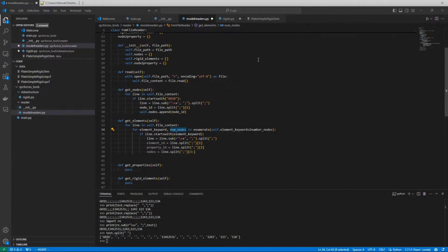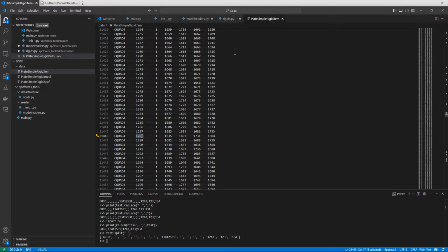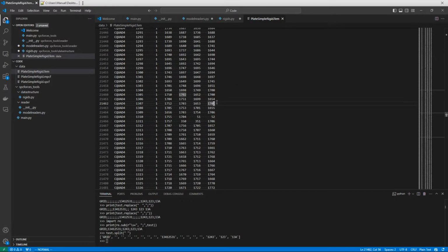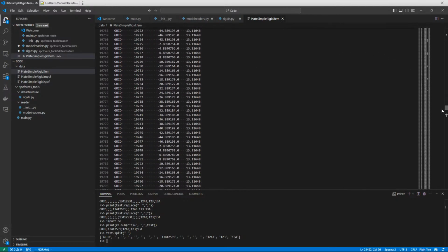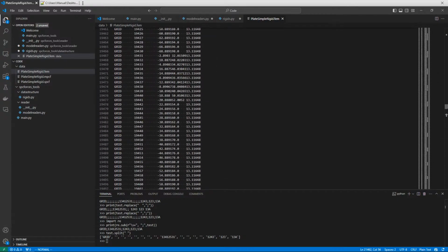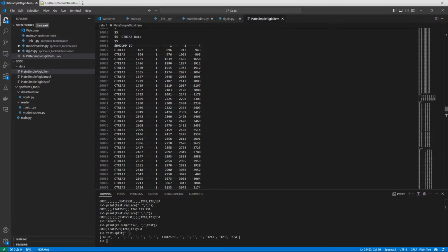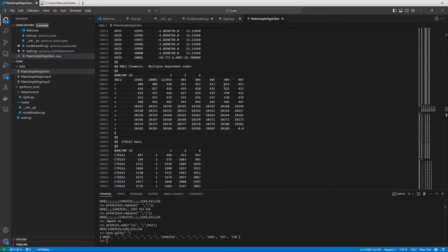By the way, I can think of something here being nasty in the future. If we have a hex element with more than 8 nodes or so, it will have another line with a plus at the beginning. With the RB2 you can see it, and you will have something like this too. So we definitely would like something which reads more than just one line.